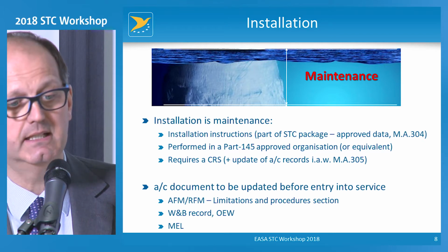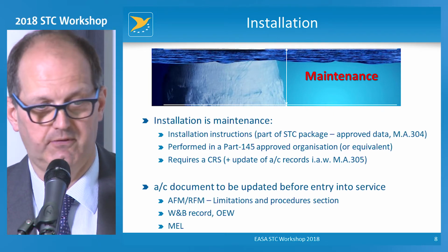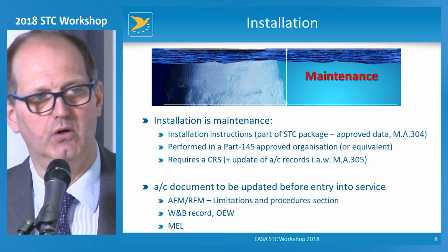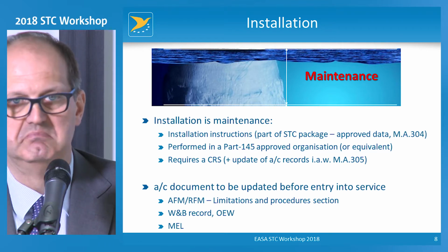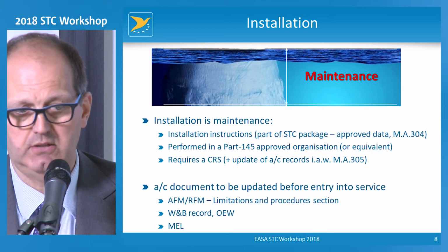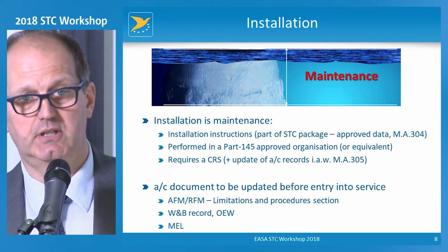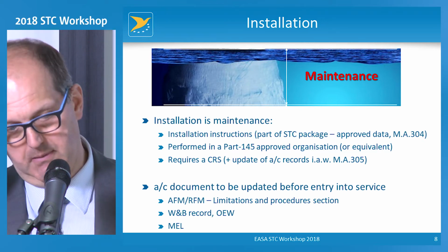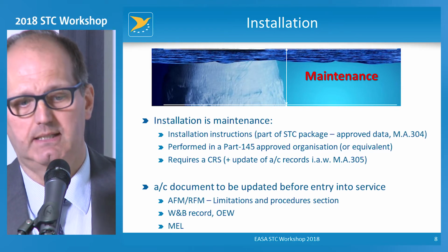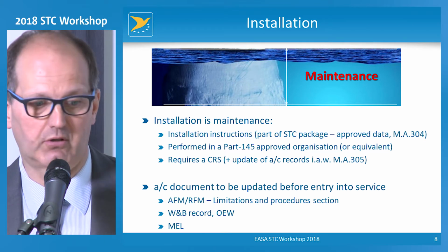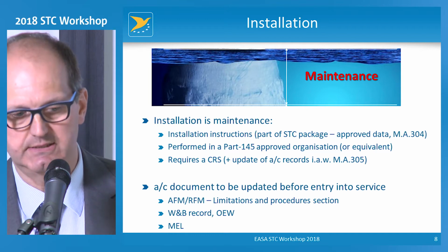And then at the end of the installation, there is a need for a certificate of release to service, which will also be reflected in an update of the aircraft records. Aircraft records are not only recording that the head-up display was installed at a certain date by a certain company, but probably that there was a supplement to the aircraft or rotorcraft flight manual explaining how it has to be used.